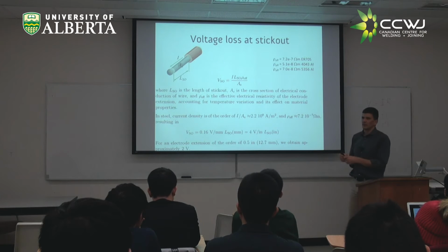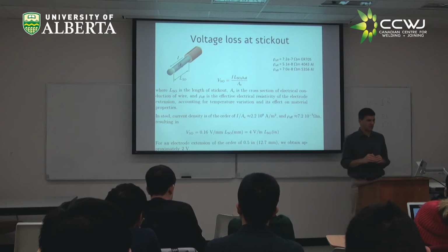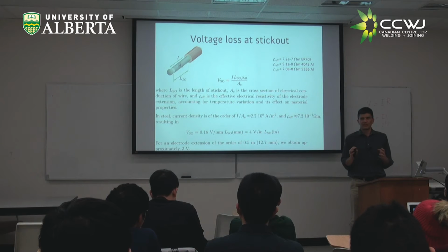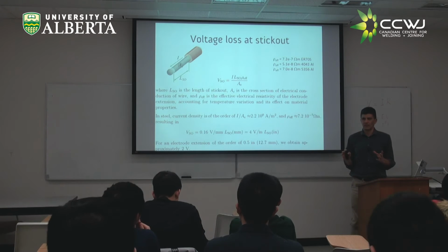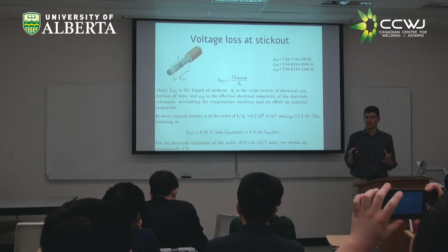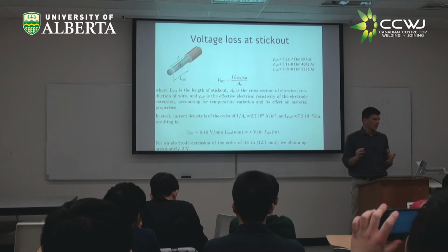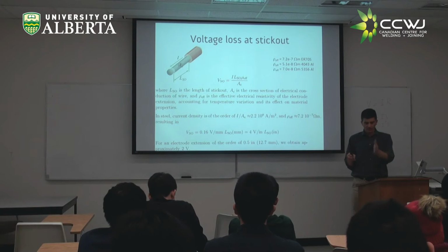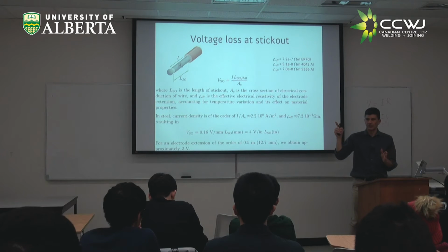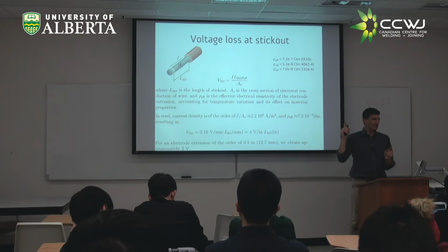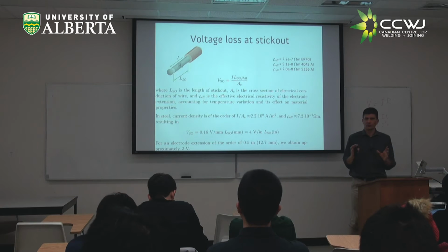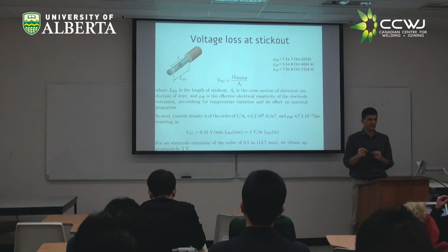The F here stands for something I'm sparing you with, but the resistivity of steel, for example, changes a lot with temperature, a lot. So you go from room temperature at the contact tip to melting temperature at the tip of the electrode. And in there, you have almost an order of magnitude in variation in resistance, right?